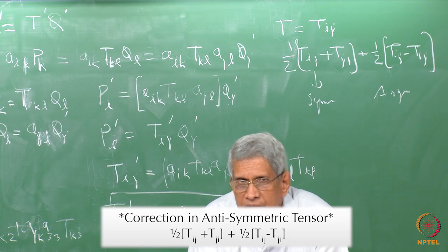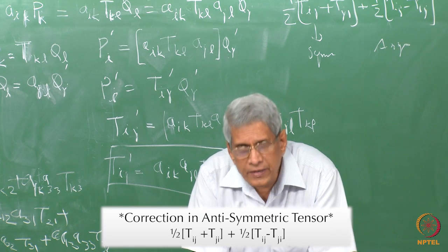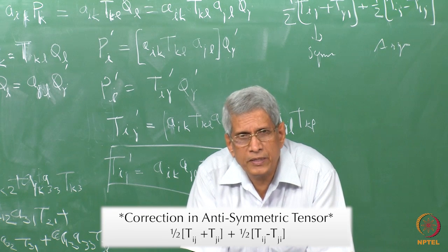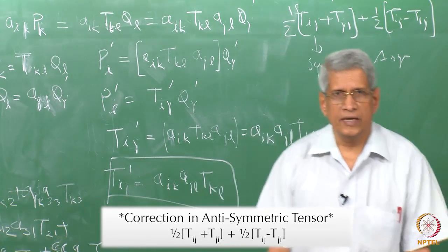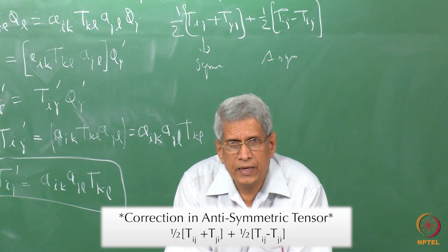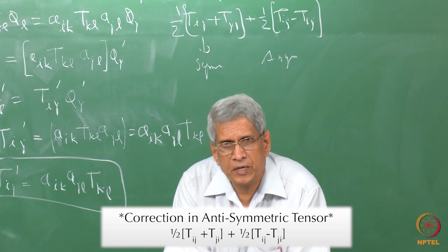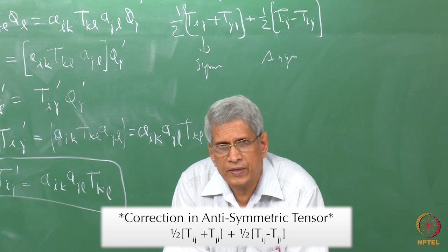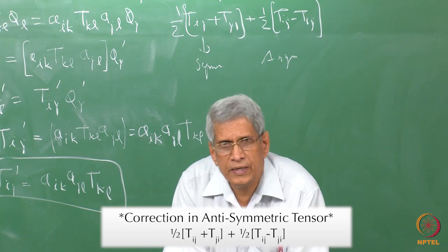And the symmetric part of the tensor, if we represent it, involves again 9 elements, diagonal elements and off diagonal elements. For example, if we consider this to be a strain matrix, the diagonal elements represent essentially the pure strain, that is dilatational, and the others represent the shear strain, right.